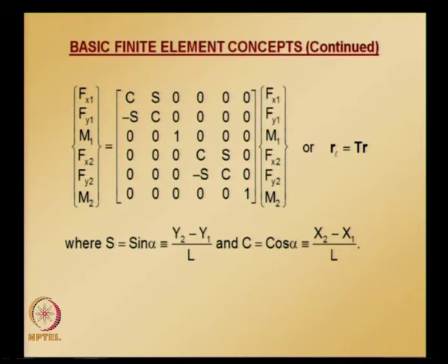And also, as in the beam bending problem or as in the axial deformation problem or truss problems, the displacements also get transformed in the same manner as the forces, and the inverse relation between the global load vector and local load vector is given by R is equal to T transpose RL, because this transformation matrix is orthogonal.